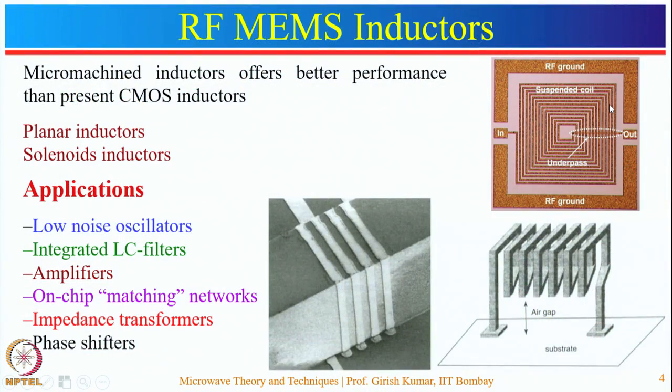The planar inductors could be of two types, spiral and the meandrical in shape. The spiral inductance can be increased by increasing the number of turns, but it increases the capacitance between the turns, which reduces the quality factor. So, it should be optimized properly. The optimum value between the quality factor and the inductance value can be selected by narrowing down the inner strips and widening the outer strips. These inductors can be easily fabricated by the current fabrication technology.